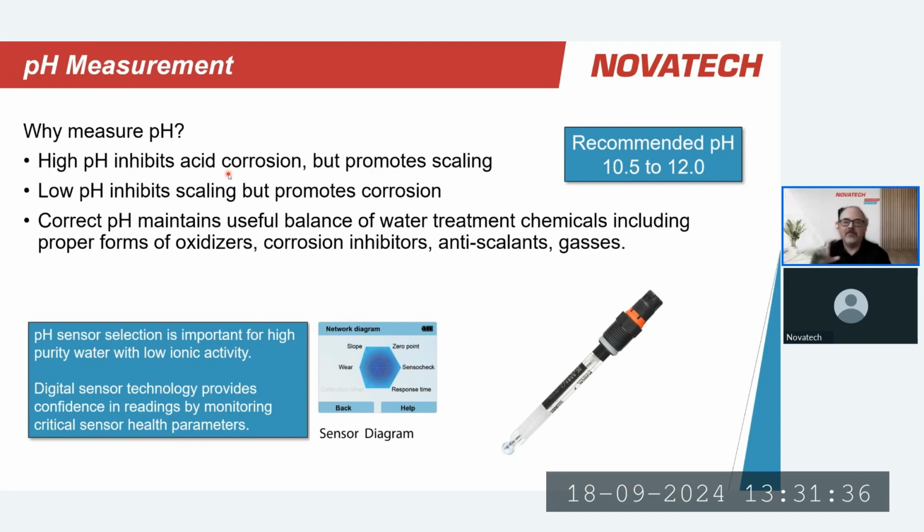So we have to think about that when we're selecting our pH electrodes, because not all pH electrodes are created equal. Some pH electrodes are really optimized for monitoring in and around natural water pH levels. So for wastewater applications or potable water applications. Others are really optimized for acidic environments. Others are optimized for these alkaline environments that we're talking about here. So choosing the right pH sensor with the right electrolyte formulation, with the right type of junction is critical to ensuring that it's going to work properly in this type of environment.